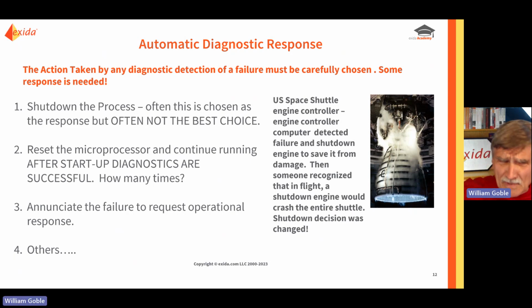Another solution might be to reset the microprocessor and continue running if startup diagnostics are successful. But you can't do that forever. There's probably some limit on how long you can do that. A common choice might be 3 times. Then you have to go to one of the other choices. And a third choice is to annunciate the failure to request operational response. In other words, I failed. Come and fix me.